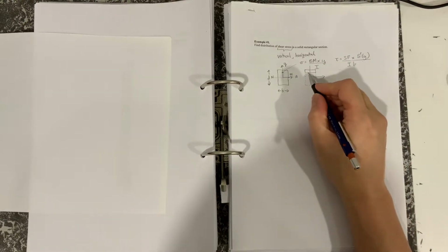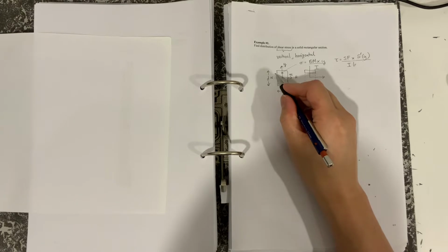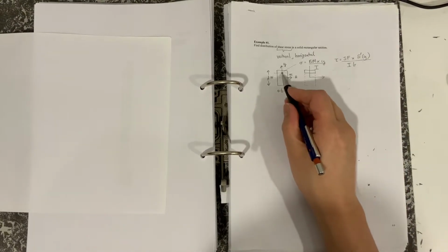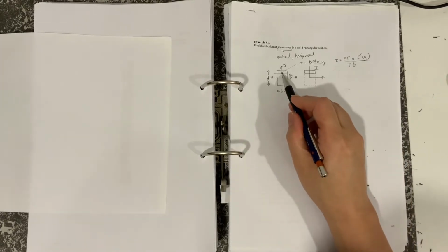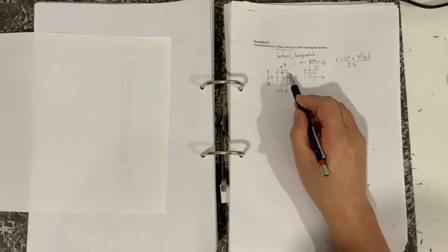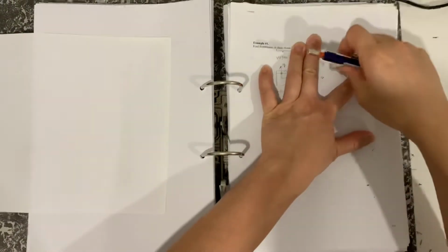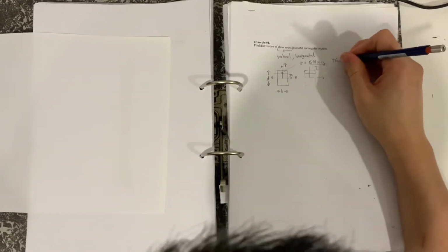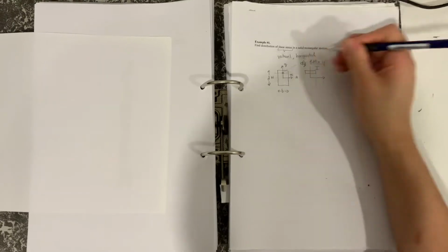And what we want to do is, we've made our slice here because it's at that distance y from the neutral axis, where we want to work out the shear stress. Incidentally, the shear stress would be the same whether it's here or here or here. So anywhere along this line within the section, the shear stress tau would be the same. Perhaps I should have said tau is a function of y as well, and sigma is also a function of y.